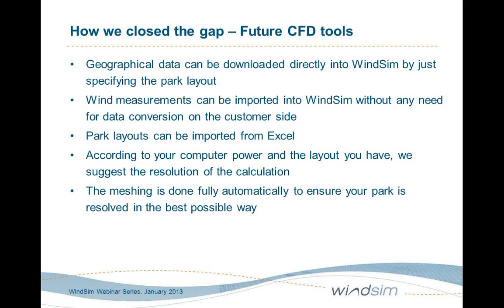What contains the WindSim Express? First of all, geographical data can be downloaded directly into WindSim by just specifying your park layout. Wind measurements can be imported into WindSim without any need for data conversion on the customer side. Then you can specify your park layout easily from Excel. And then, according to your computer power and the layout which you have given to us, we suggest you the resolution of the calculation. Then the meshing is done fully automatically to ensure that your park is resolved in the best possible way.